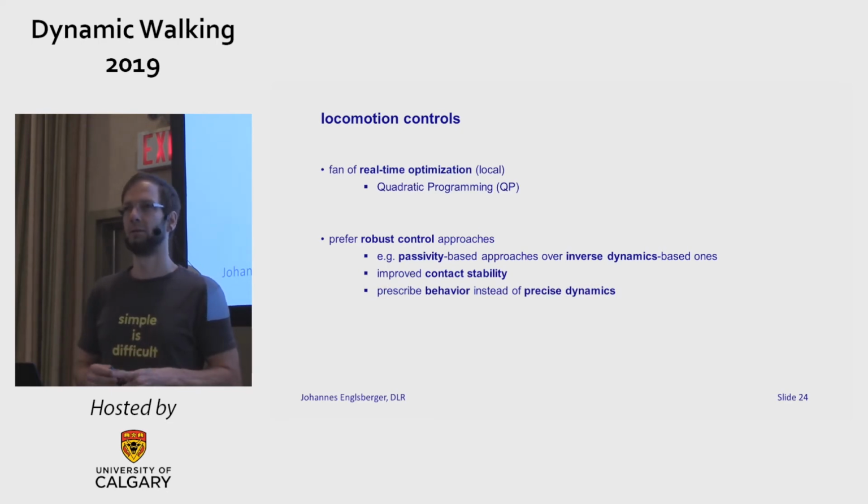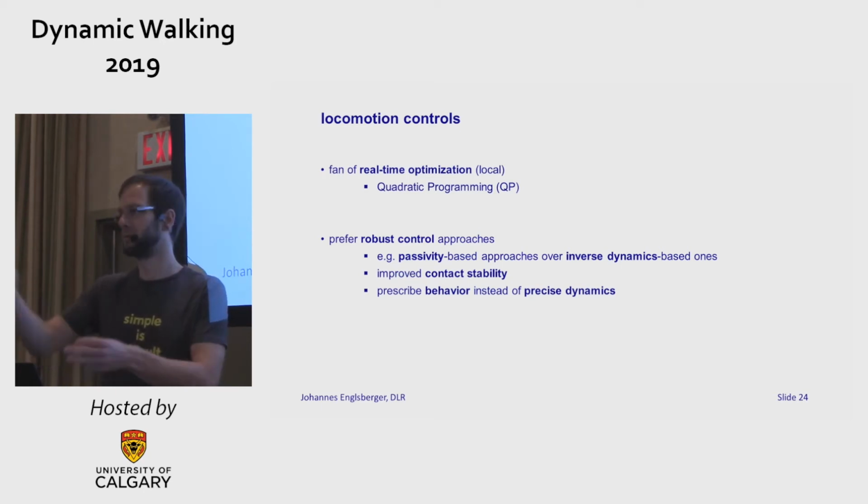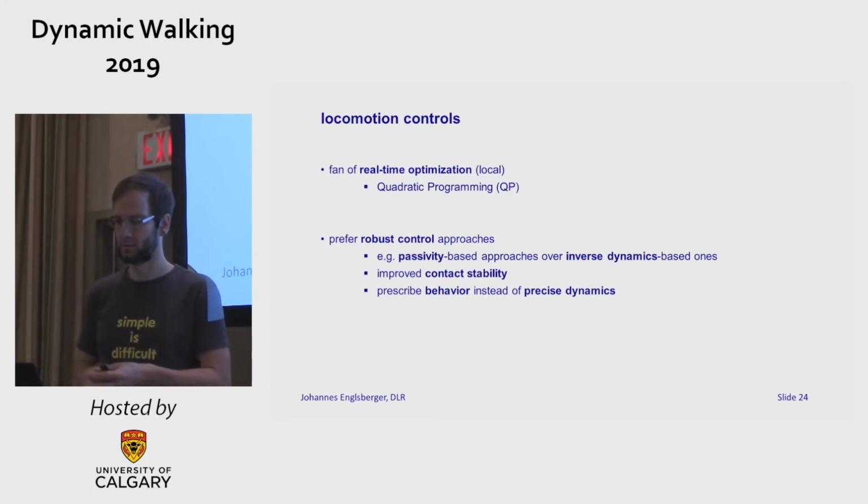Why that? In my opinion, inverse dynamics tries to strongly prescribe what the dynamics is supposed to be. For example, the stance foot is supposed to not accelerate. If it accelerates anyway, because maybe there's a little step or trip, or for example on the mattress, if it accelerates although you were thinking it's not accelerating, then this prescribed physics is wrong, and then stuff messes up.